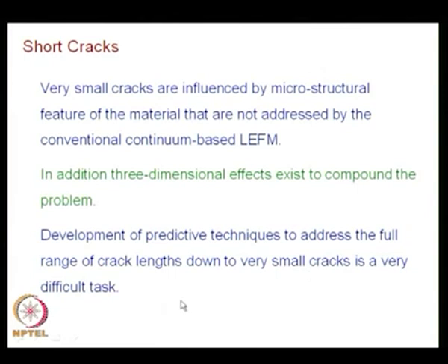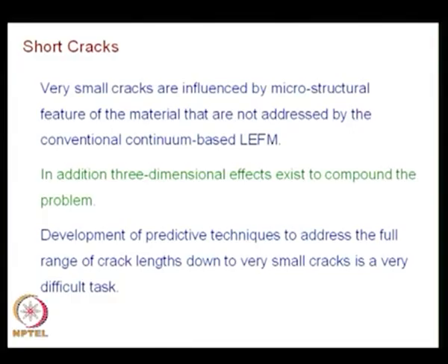You have to understand that. You develop linear elastic fracture mechanics so that we have a comfort zone, we understand how reasonably long cracks behave, and we are able to solve a certain class of problems. So, that is only limited knowledge. Any predictive technique to address the full range of crack lengths is very, very difficult.